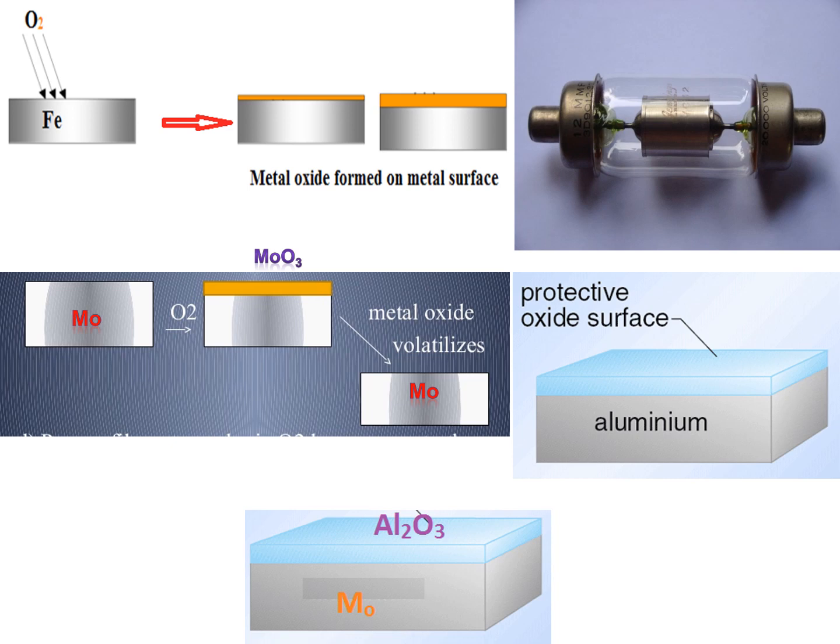And the next thing is, if you keep a metal in a vacuum, what will happen? Even if you observe for a long time, the metal doesn't corrode. Why? Because in a vacuum there is no atmosphere, no gases or moisture to contact the metal. Corrosion is nothing but oxidation, meaning loss of electrons. The lost electrons will not be accepted by anyone. That's why oxidation will not occur separately, and corrosion doesn't occur when you keep a metal in a vacuum.